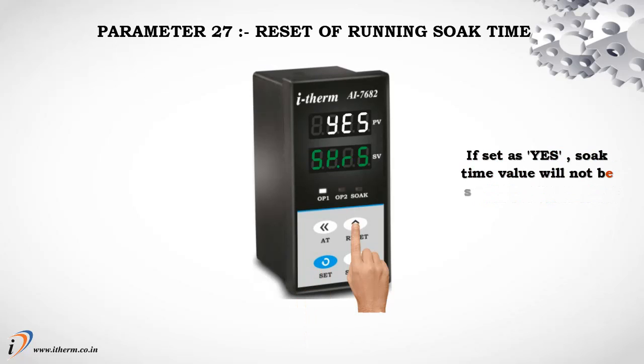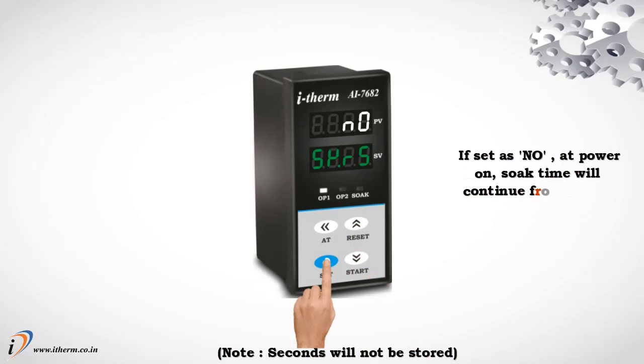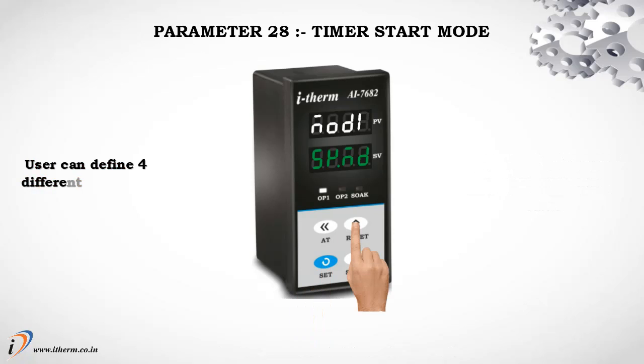Parameter 27, reset of running soak time. If set as yes, soak time value will not be stored at the time of power failure. If set as no, at power on, soak time will continue from stored value. Parameter 28, timer start mode. User can define 4 different modes to start the soak time.